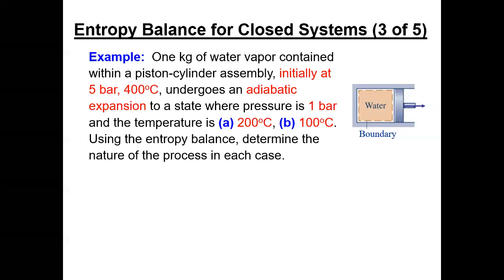And so you've only got 2 terms here to work with on the overall entropy change. And the only one that can go down would be heat transfer out, a negative entropy transfer. But if you say it's adiabatic, you eliminate that possibility. So that term is going to be 0, and the other term is 0 or greater. So it can't be negative. It's not going to happen.